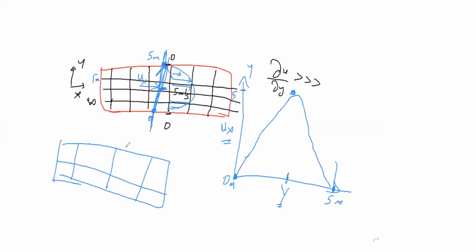No, sir. Right? Because there are only 3 points you'll be getting, one here, one here, one here, which will be a triangle. Only 3 data points you have. So basically, to capture any physics, make sure that you are having at least 10 cells.